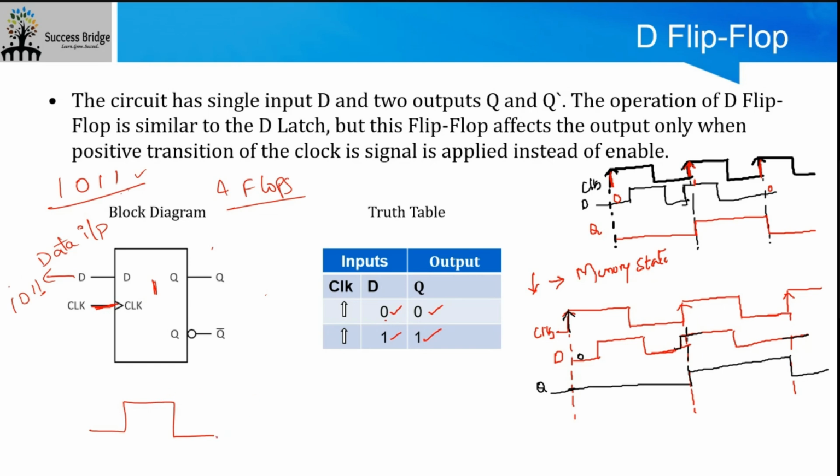If you give one more clock pulse, the next value will come and this value will move on to the next cascaded flop, if there is connectivity. If not, it will just go to a combinational logic gate, if there is one, and be captured in the output.